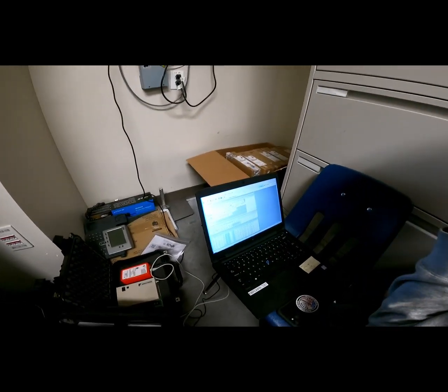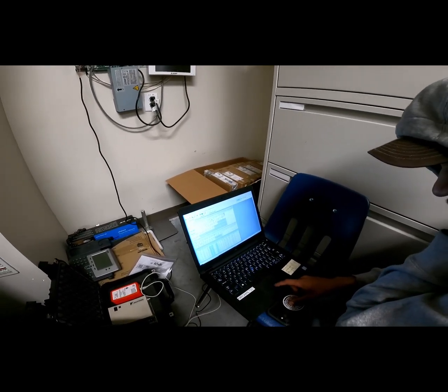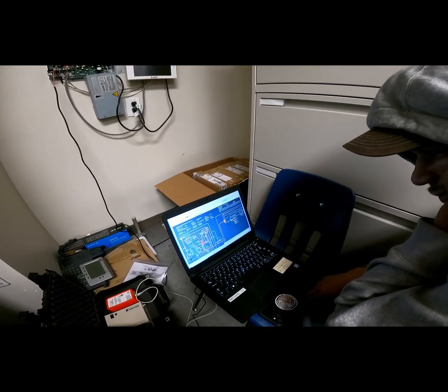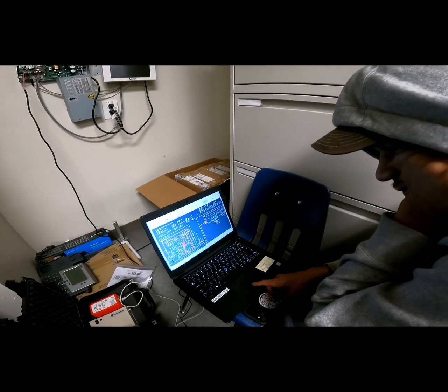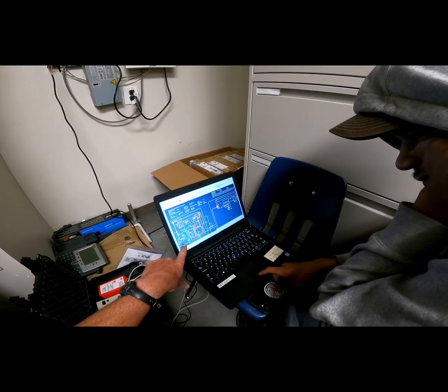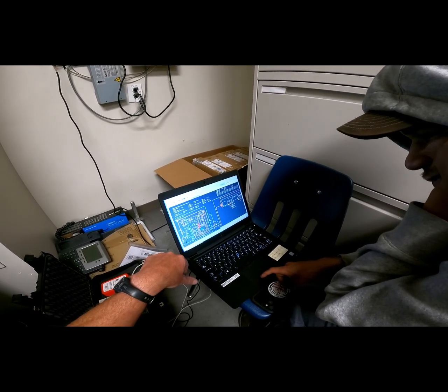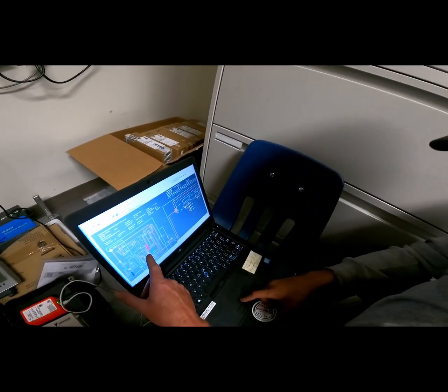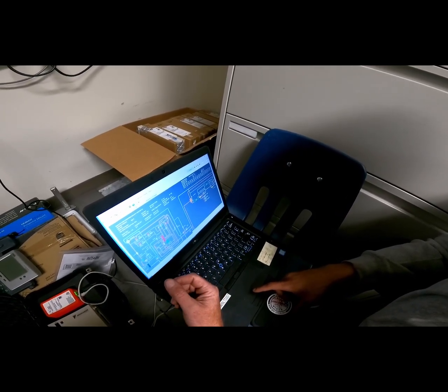Now, one other thing you can do while you're performing this test is click up here on refrigerant circuit diagram. This is going to tell you how the refrigerant's flowing visually. So instead of looking at a bunch of data, you could actually see what's happening. You've got a compressor right here with a discharge temperature TH4 of 154 degrees. These are your, they call them heat exchangers, but right now this is your outdoor coil.